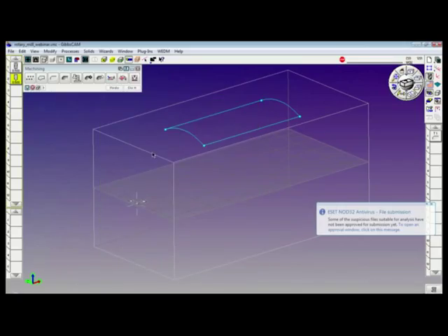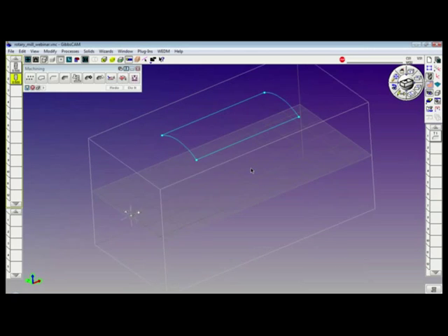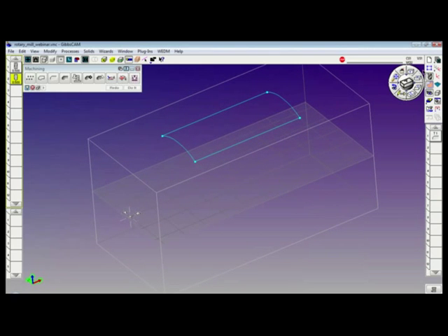In order to drill, we need a point on screen. So open the geometry creation palette, select the point tile, XYZ, X1, and notice that my dialog says XAR. The reason it says XAR is because I'm in rotary mode.